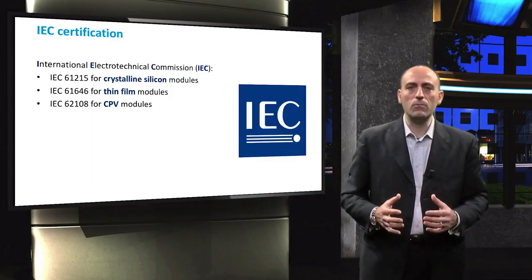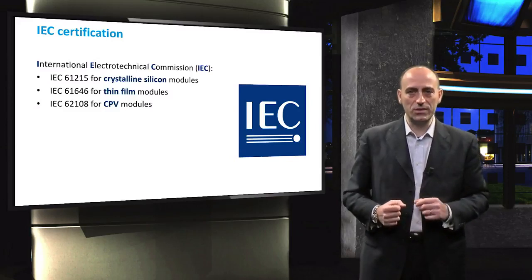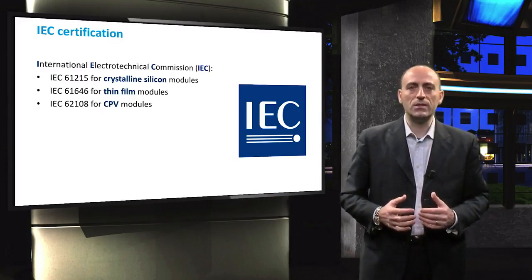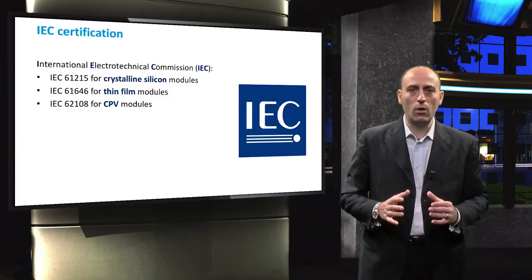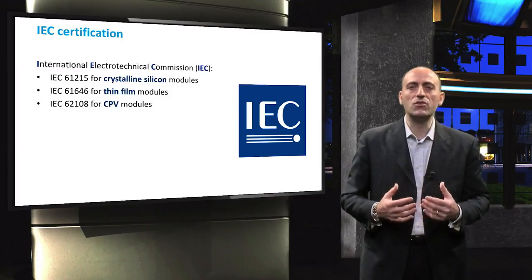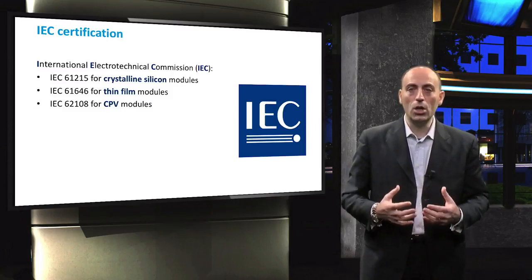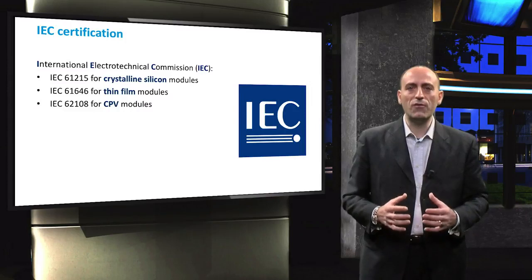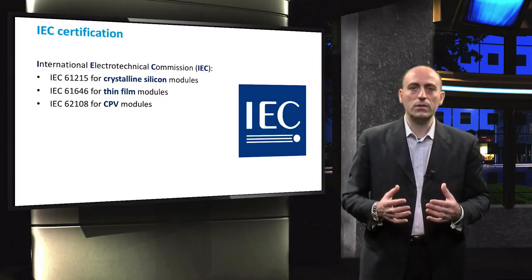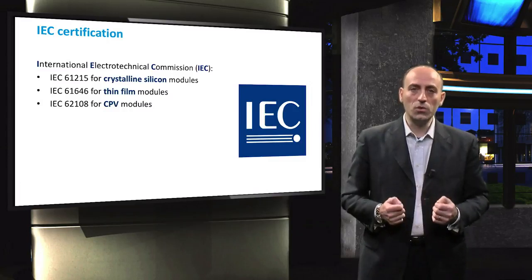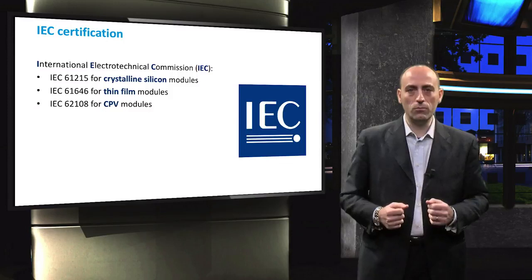In many markets, PV modules are required to pass the IEC certification before these modules can be offered on the market. Thus, the IEC certificate ensures a minimum level of quality of the modules. The modules that pass the IEC qualification are less likely to have design flaws and thereby are more likely to endure outdoor operation. However, the qualification was designed to identify premature failure. Thus, this standard only tests if the modules pass a minimum requirement. It does not guarantee that it will last throughout its lifetime. Also, it does not predict a minimum lifetime of the modules.